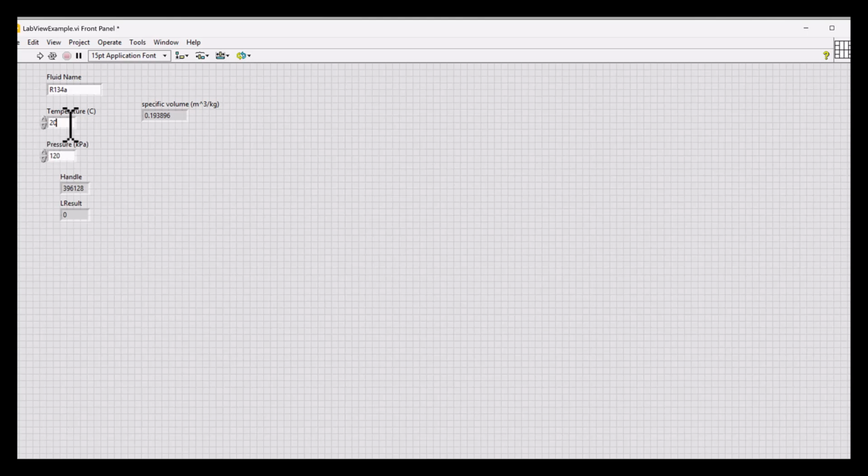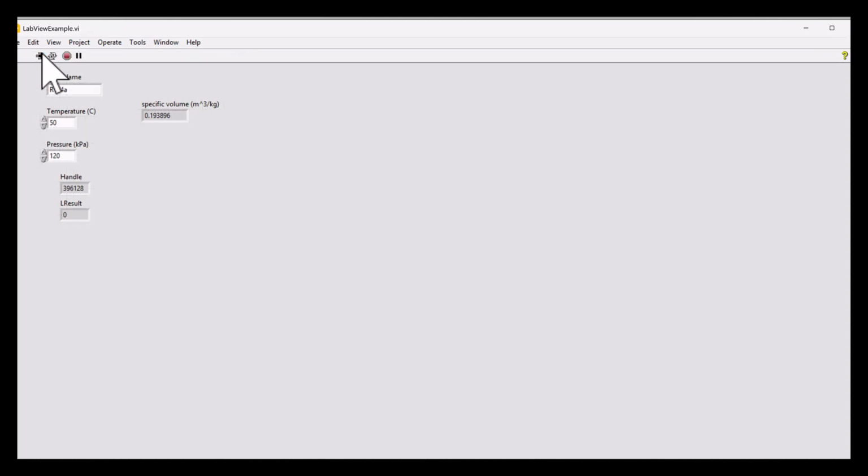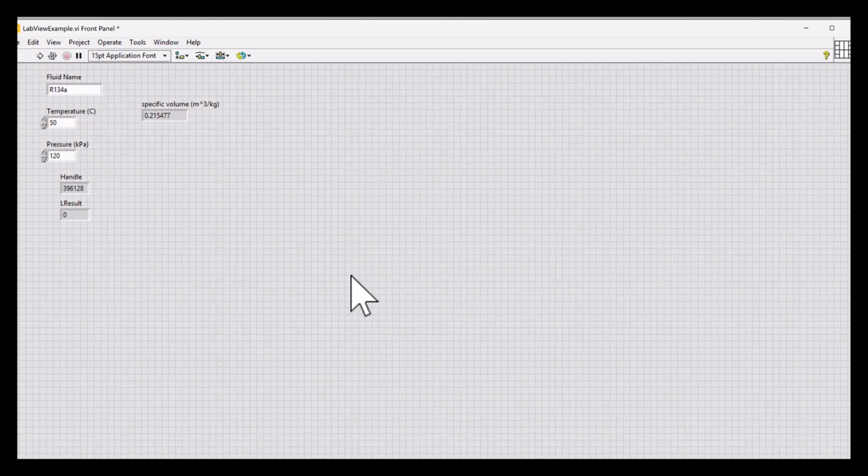And you can do all kinds of things with this, obviously, right? This is pretty trivial what I'm doing here, but you can see how as you're taking data now, you can reduce that data in EES if you want to have access to some of the capabilities of EES for that. You could, if you wanted to, take the data, plot it on a TS diagram or something like that, and then save the TS diagram and have that be loaded into your LabView code. You can turn this whole thing into a sub VI that just gets called, so it's very easy to execute this whenever you want to access some capability of EES.